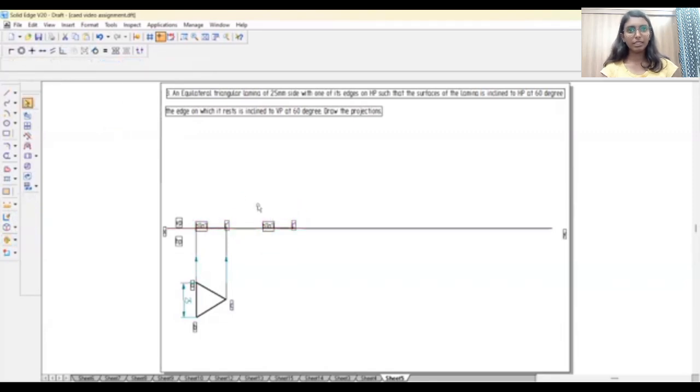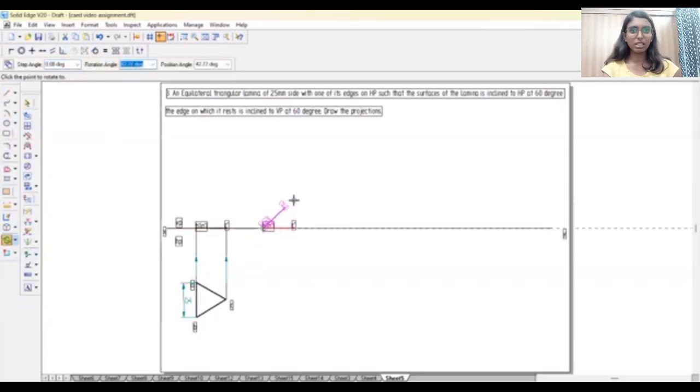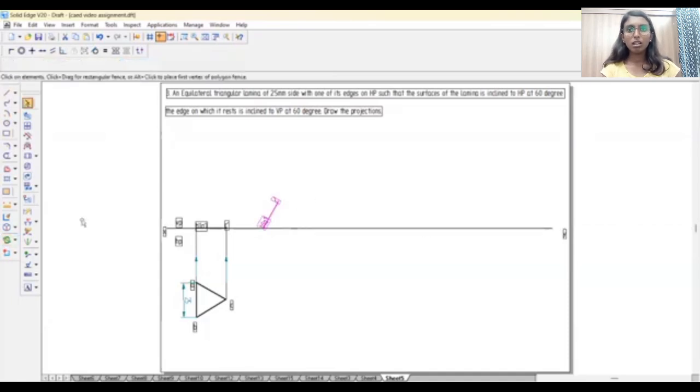After rotating, let's project the line with 0.13 mm thickness to the top of the XY line, and the tip point also to the XY line. Now let's take the leader option, facing the XY line, so arrows are towards up.